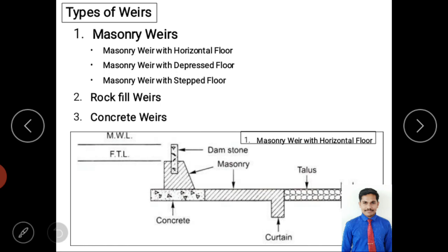In the first image, maybe you are getting some confusion, because it is a cross section. When you take a cross section of a weir at some particular place, it looks like this. This portion is under the bund, on the side of the bund, and after the bund there will be an apron or bed, as I told, to handle the wear and tear or erosion of the bed. Here the bed is provided, and this is the bed portion, nearby the bund.